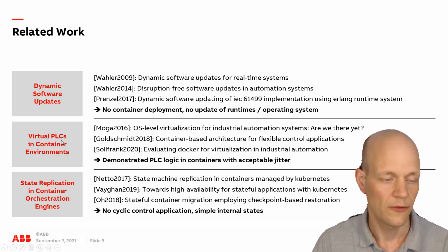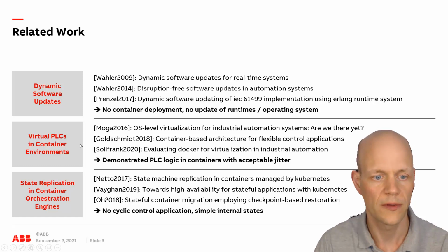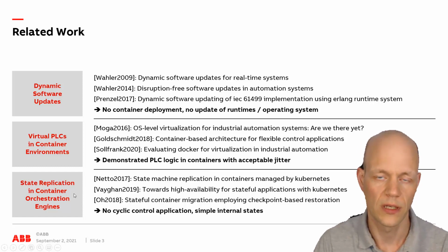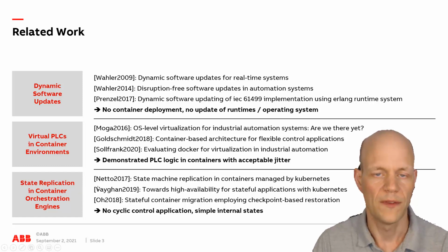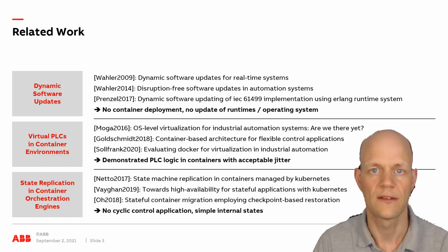And then there have been works looking at putting PLC software, these programmable logical controllers, into container environments. Different works here, they essentially demonstrated that the PLC logic can be computed in such containers with acceptable jitter. And finally, there are some newer works on state replication in container orchestration engines, but these are mostly targeting web application, consumer applications, which are not executing cyclically and have usually simpler internal states, like a few client parameters.